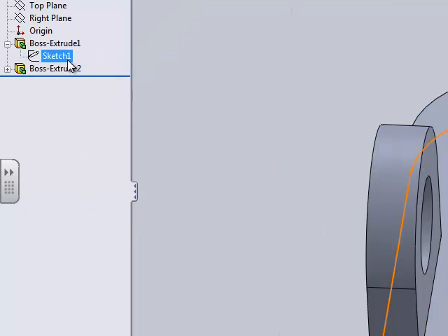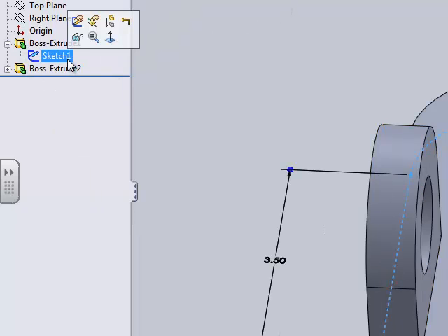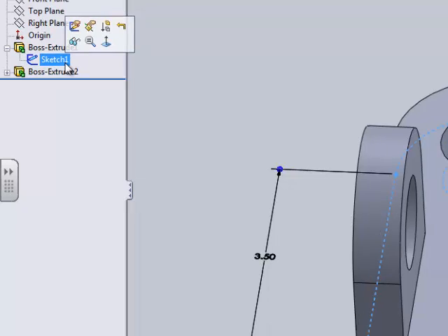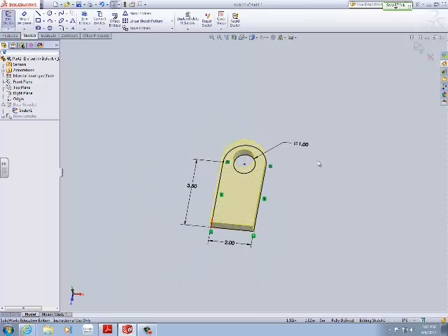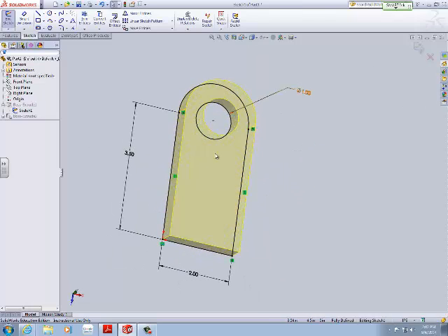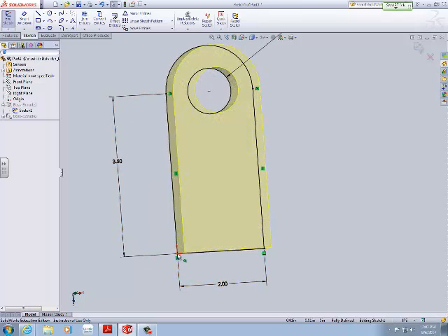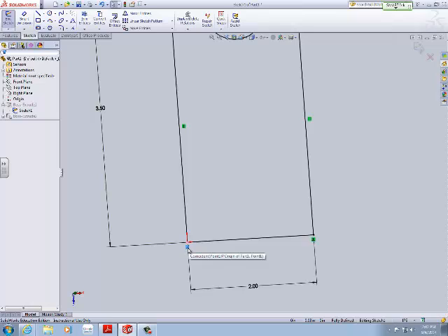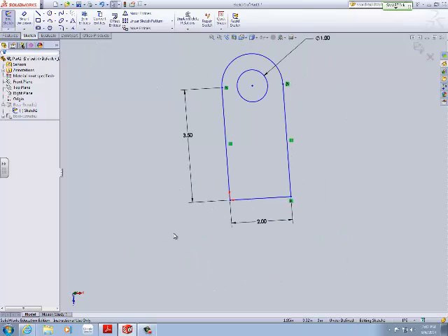So I'm going to backtrack to our first drawing, which is standard. Everything you design in SolidWorks, you will always backtrack and fix something, move something, change something. That's how it goes. That's what it's all about, engineering. So we're going to go back to our original sketch. Go to Edit Sketch. It's still showing me as extrudes. That's right. And we're going to delete this relationship. So we're going to select that marking right there, and you're going to use the delete command on your keyboard, or you can right click and delete completely.